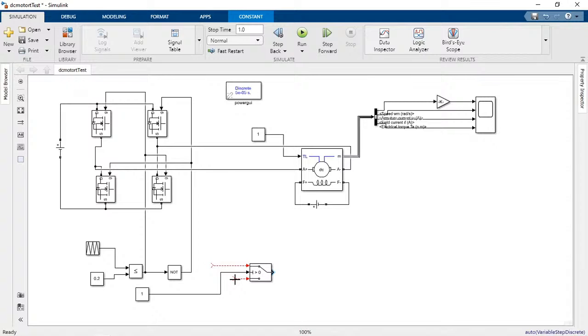So now, for motoring applications, you have to directly apply the PWM to these MOSFETs. For braking applications, you have to turn off the top switches and then enable the bottom switches. If you enable both the bottom switches, then the back EMF available inside the motor will be dissipated within the motor itself. In that condition, the speed of the machine will drastically reduce and approach 0. So that is the idea for the braking.